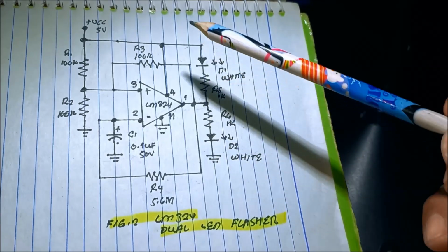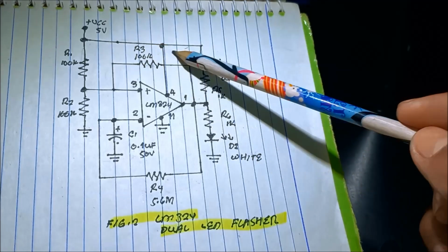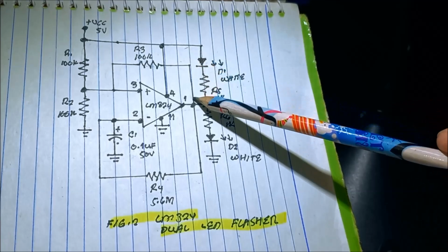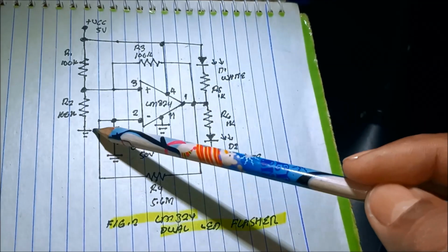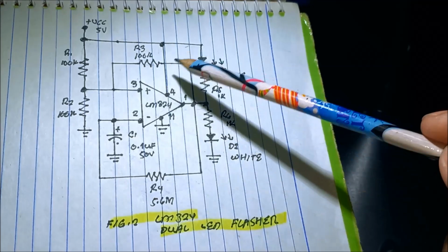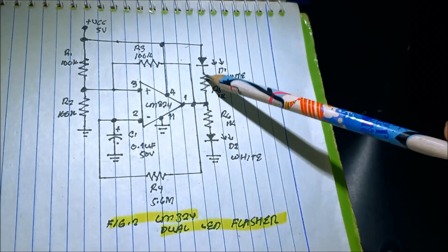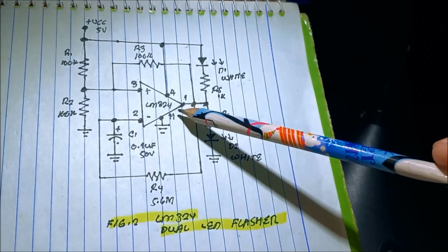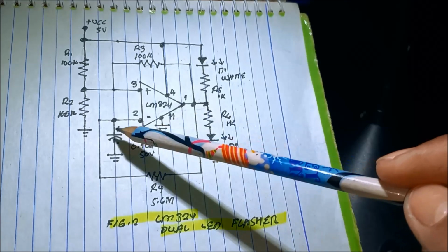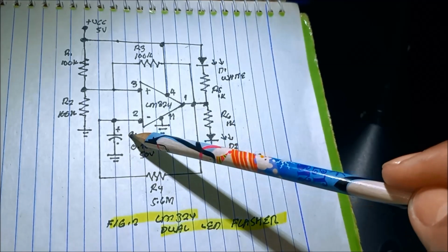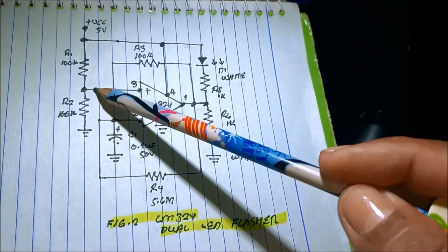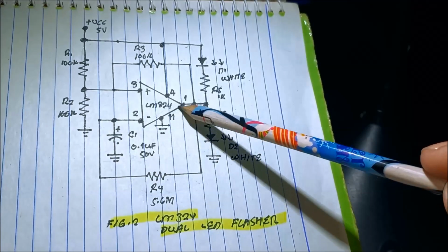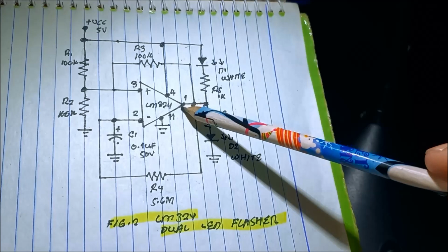LED1 and the LED2. So the initial state of the circuit is when the capacitor is charging, it charges through the R4 and then to the capacitor. So it charging the capacitor, causing this LED to turn on, because the output of the op amp is in a low state. Because the capacitor is charging, it develops a voltage greater than the voltage reference 2.5, causing this to enter in the low state or zero or low level.